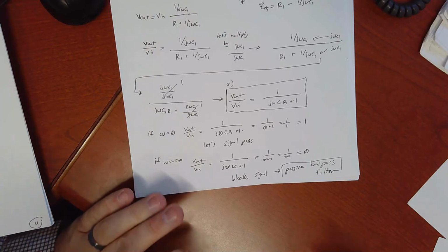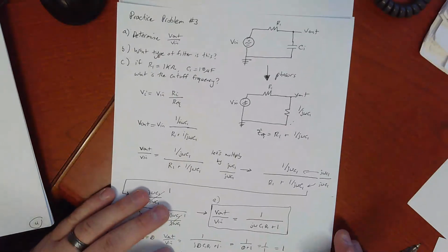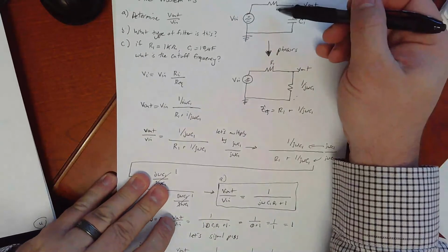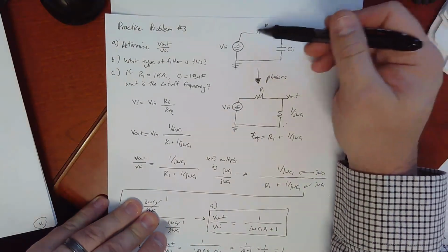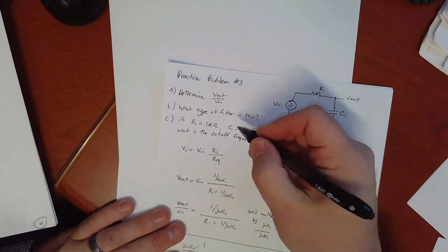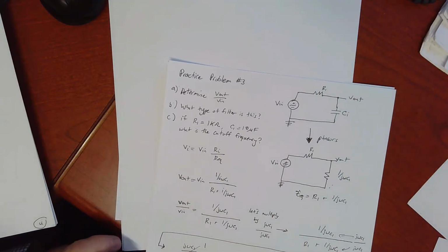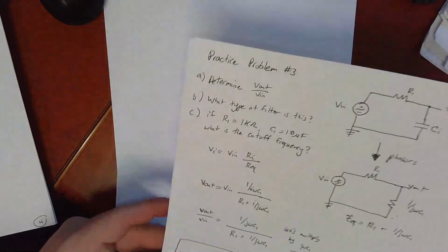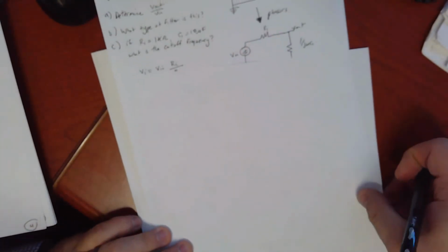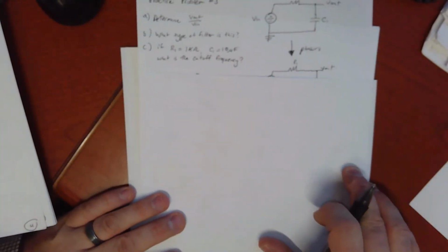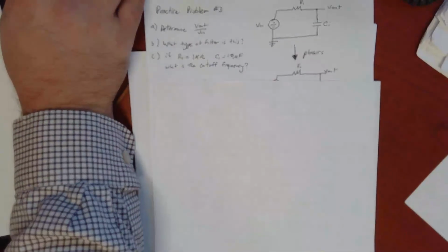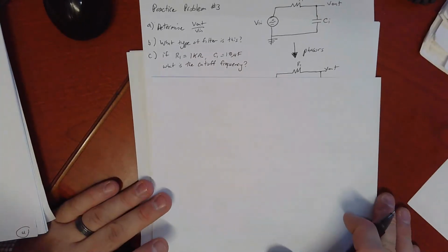And if you're not sure, you can always check. Say, okay, what happens to these things? You just plug it in and understand. But generally, if you have a resistor connecting output to input, at 0, something's going to flow. Now, part C is asking, what is the cutoff frequency if we have those values? So let me rearrange just a little bit here so we can see all of this at once.